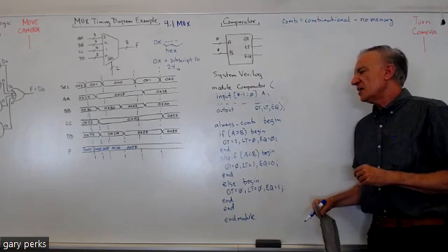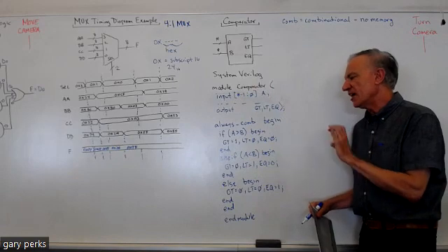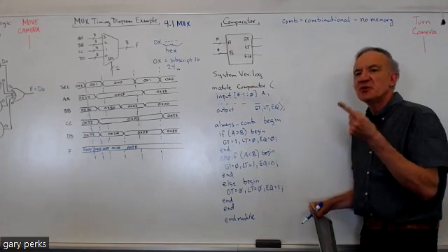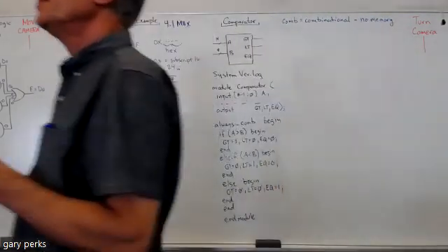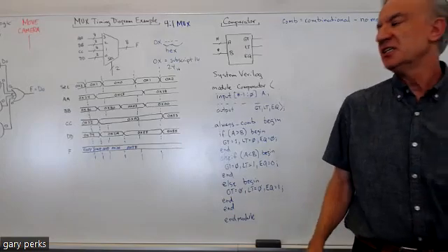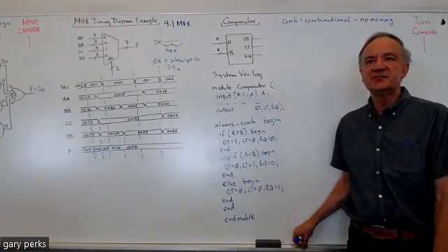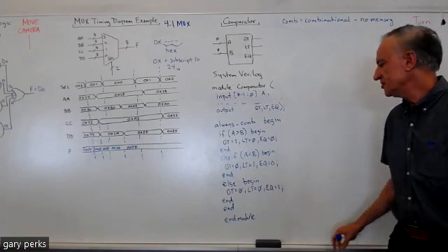A lot of times where you'll get errors is you got to make sure you have an end for every begin. Sometimes people will have an extra end or they'll miss an end. So watch out for that. You have a question? Does what matter? No, it doesn't. It's for readability. It's a good idea to do it for readability, but white space doesn't matter in SystemVerilog. So you can have as much white space as you want, or as little. But I always recommend using indentation just for readability. You've probably heard that before in your other programming classes.